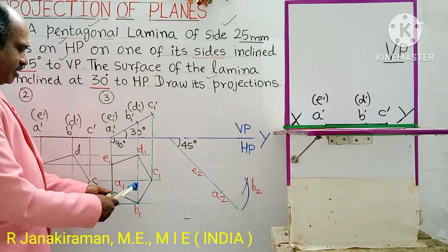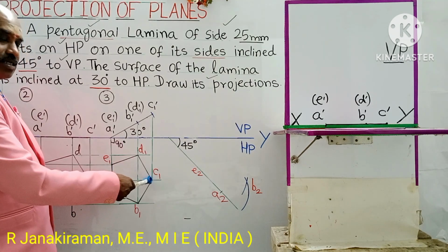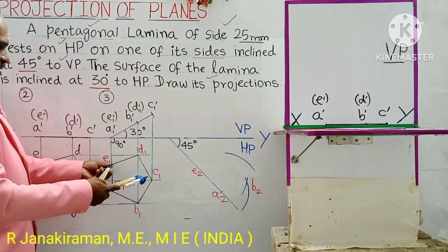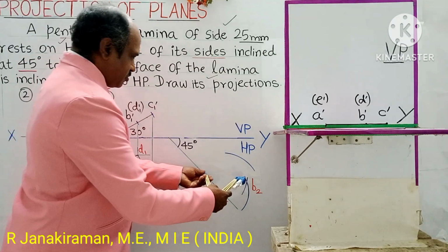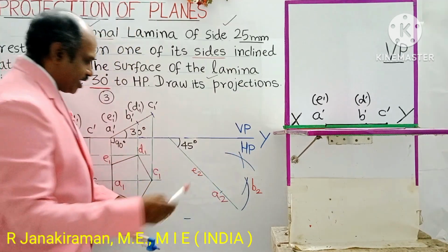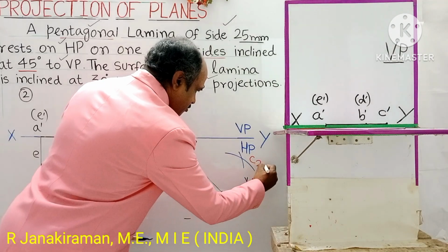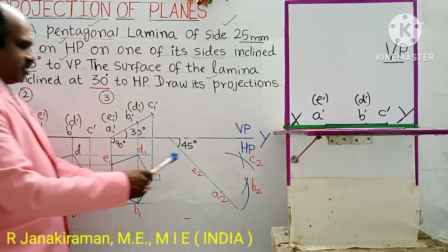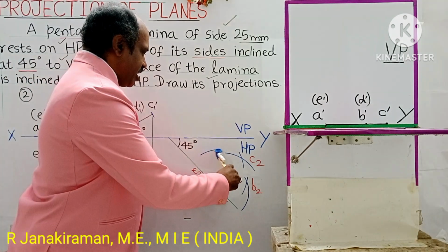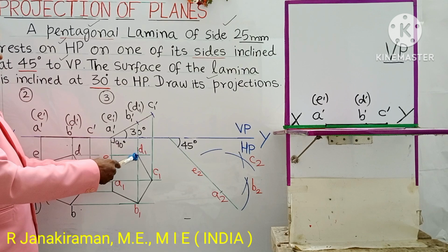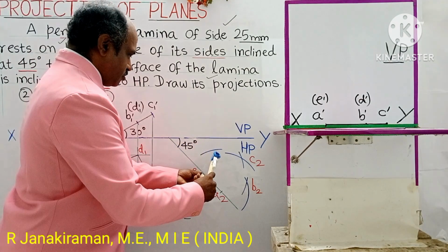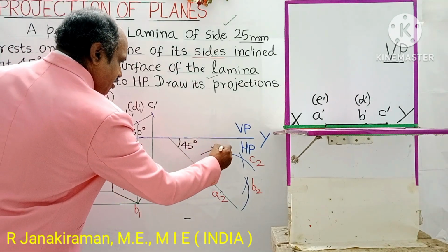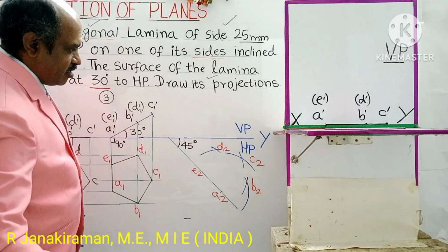Similarly, the A1, C1 distance is taken in the compass, and you copy paste the same. Next, E1, C1. Both arcs intersect here, shall be marked as C2. Next to C is D. Draw an arc. Similarly, the E1, D1 distance is taken in the compass. These arcs intersect here, shall be marked as D2. Next is E, which we have already marked.